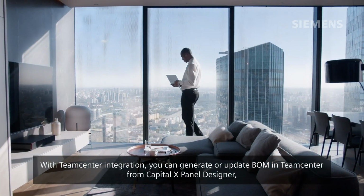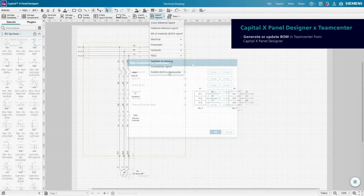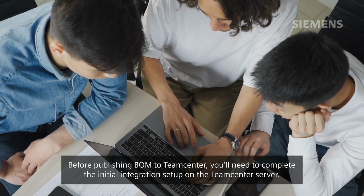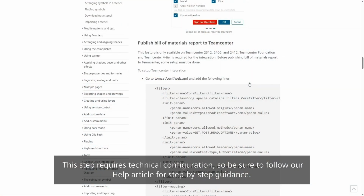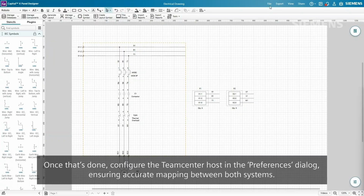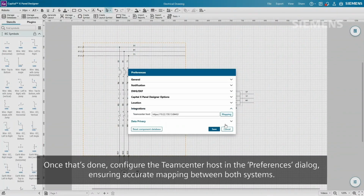With Teamcenter integration, you can generate or update BOM in Teamcenter from Capital X Panel Designer and also create and assign components from Capital X Panel Designer to Teamcenter components. Before publishing BOM to Teamcenter, you'll need to complete the initial integration setup on the Teamcenter server. This step requires technical configuration, so be sure to follow our help article for step-by-step guidance. Once that's done, configure the Teamcenter host in the Preferences dialog, ensuring accurate mapping between both systems.